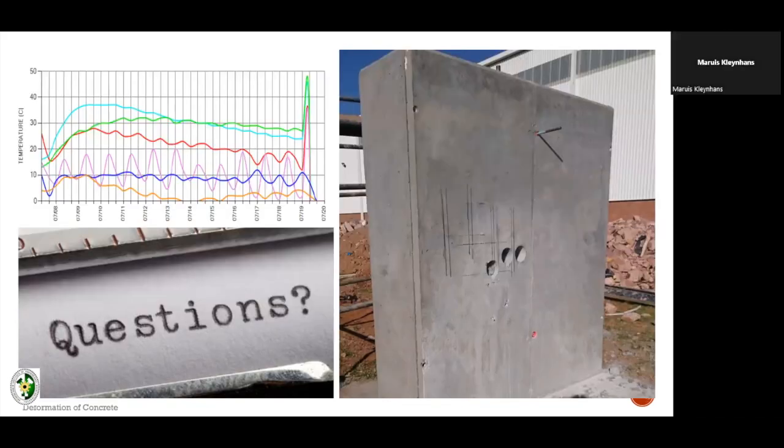Hi, Rian, it's Morris here again. It's not in particular the chloride attack. It seems to me that if you can get your concrete mix design to use less water, it's better for the concrete overall.